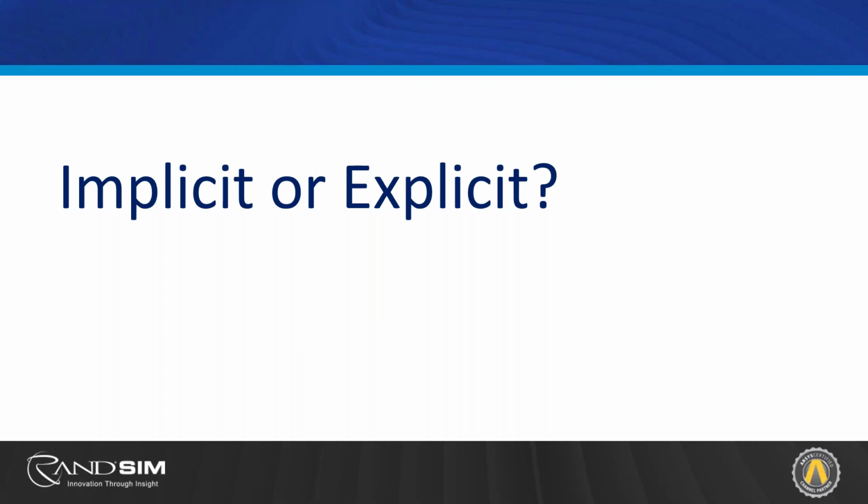You might look at this and go, oh, great, my program doesn't need to do this complicated matrix math, this complicated linear algebra. It doesn't need to go through conversion steps, so it solves much faster. Why wouldn't I use explicit dynamics for everything? And the reason why is because each analysis method has its strengths and its limitations.